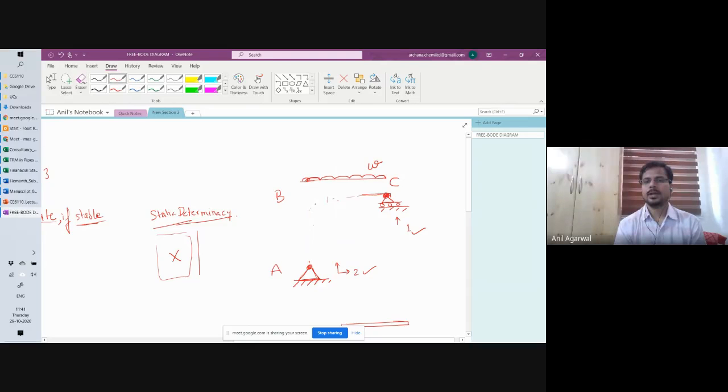And you can never cut it into too many parts. So whenever you have a doubt, you can always cut it further. So let's say this is again that old rigid structure, a rigid joint, and I cut here. I can cut it in 3 places, let's say. Then if I cut it into 3 pieces, reactions will be 3 here, 3 unknown forces each. 3, 3, 9 plus 3, 12.